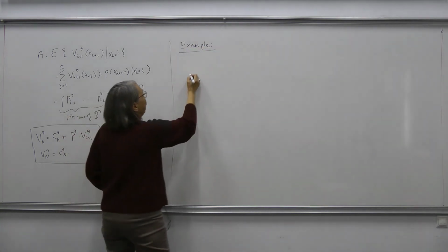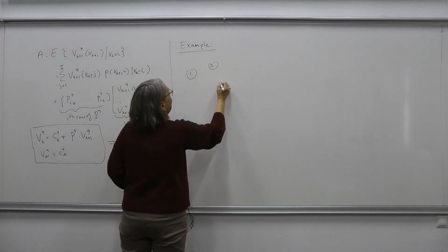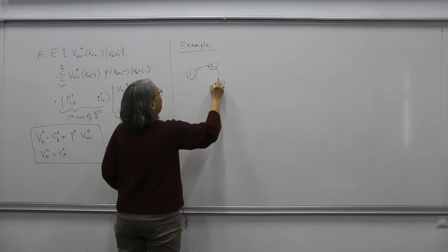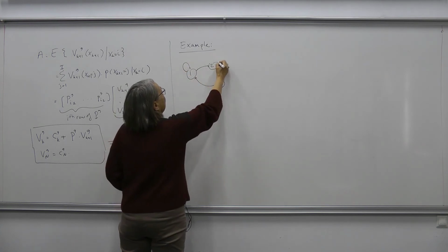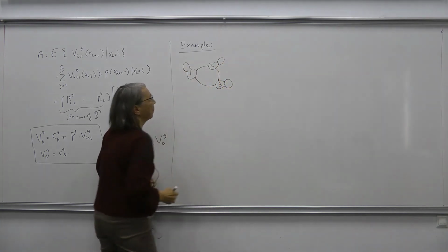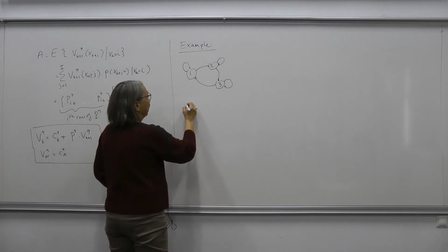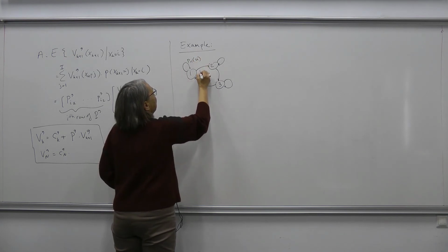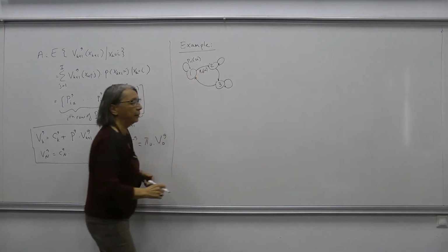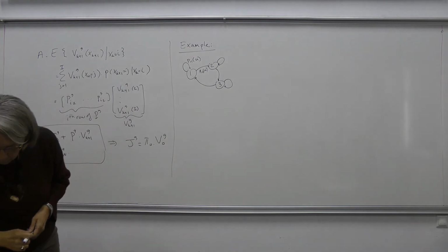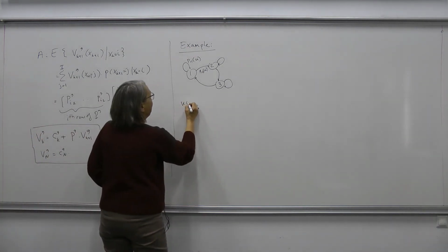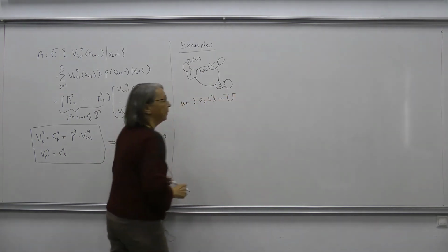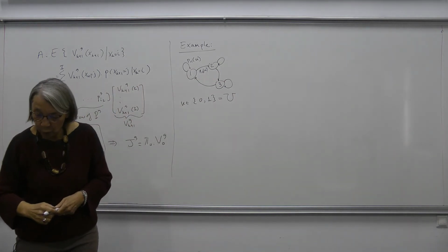In the example, we have a three-state controlled Markov chain. We have those kind of transition probabilities non-zero, and the others are zero. And therefore, we have a P of U matrix. These are all dependent. For example, this is P11(U), this is P12(U), etc. They all depend on U in our example. And U is selected as a member of the set 0 and 1. So that is our capital U set, the feasible set of all inputs. We have two inputs only for that one.